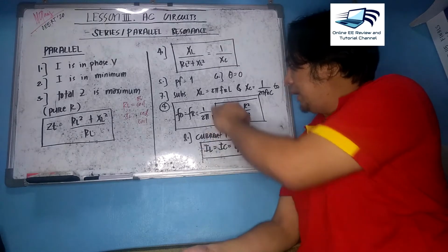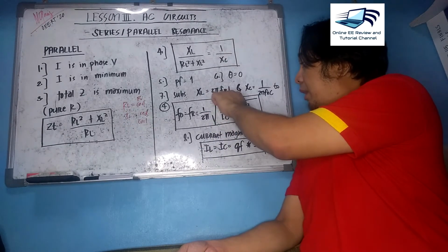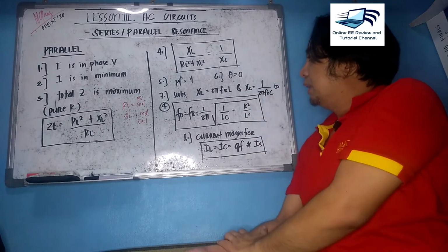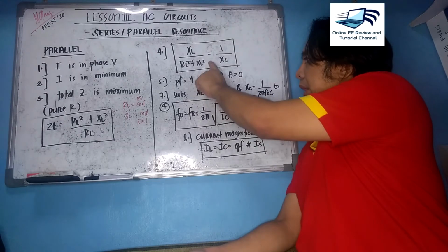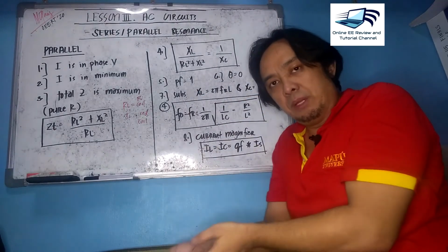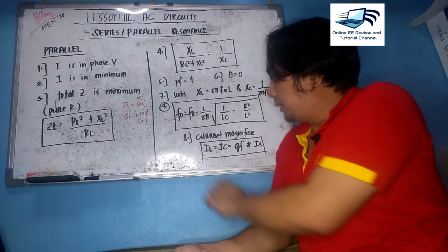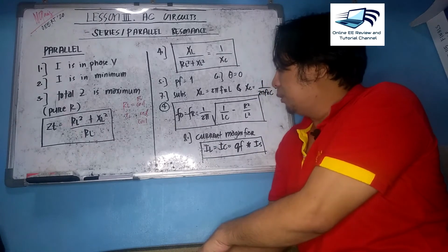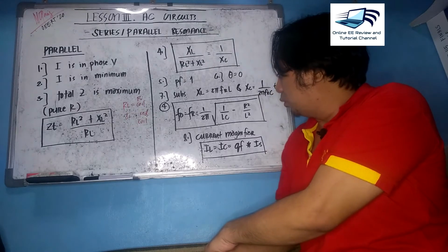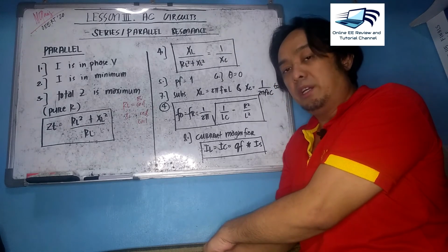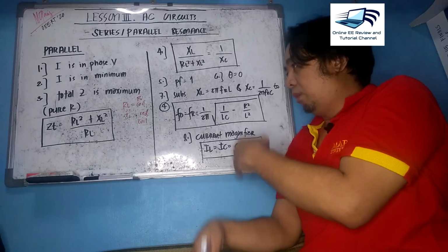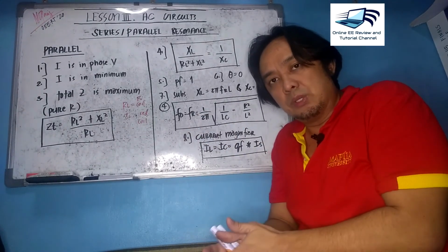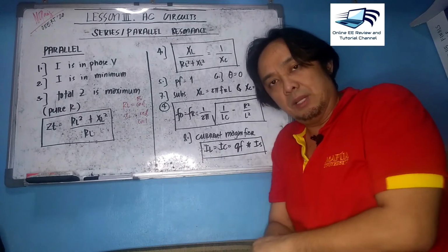If you substitute XL equals 2 pi FR L, and XC equals 1 over 2 pi FR C, into equation number 4, and simplify using a little bit of algebra, you get the oscillating frequency, equal to the resonant frequency, which is 1 over 2 pi square root of 1 over LC minus RL squared over L squared. All of the formulas in the box are very important, so if you have the time, jot them down.